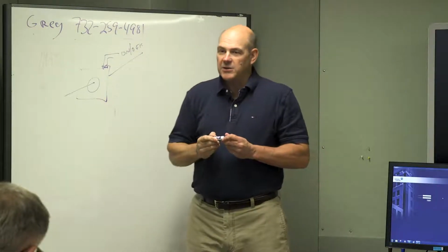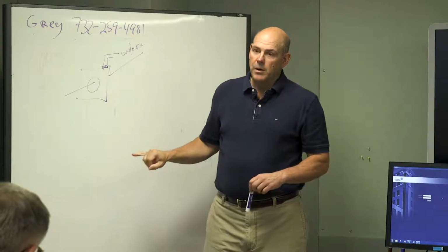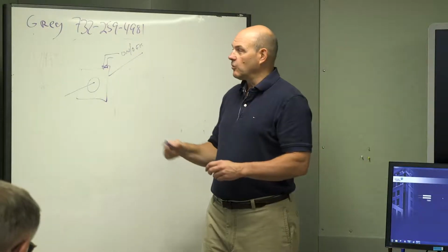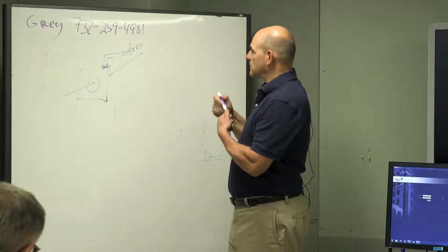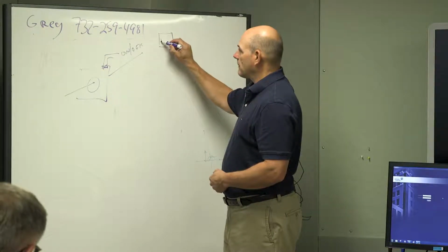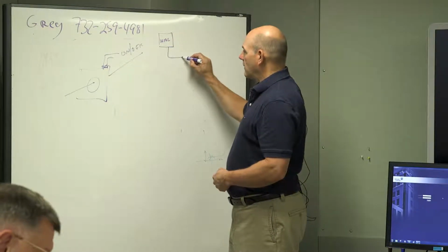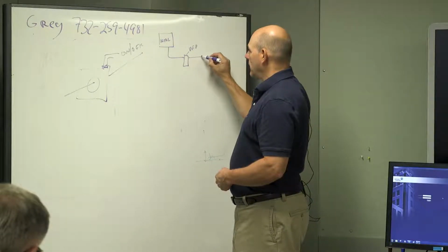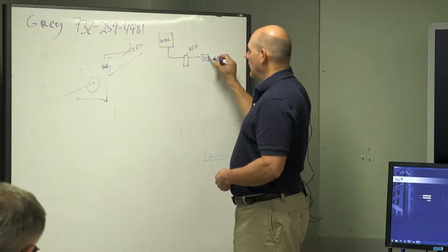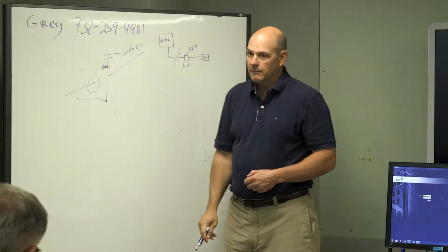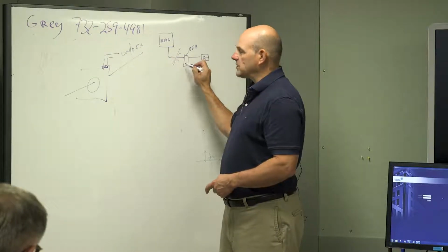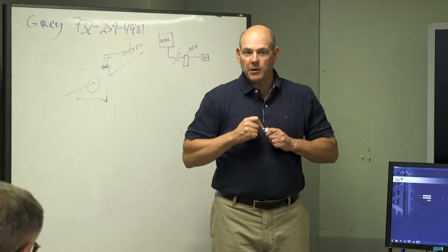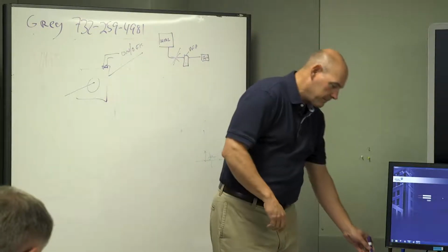So you can get that information when you click on the VFD, but we find it's critical that certain ones are hardwired. So if you lost communication to the drive, the wire gets cut. Remember how we had the NAE here? And then the wire comes here, and it could go to a VFD, and it can go to the next controller, an FEC. If this wire was cut, we still have hardwired points to that drive that you could still control the drive. That's the purpose of having some of them hardwired.